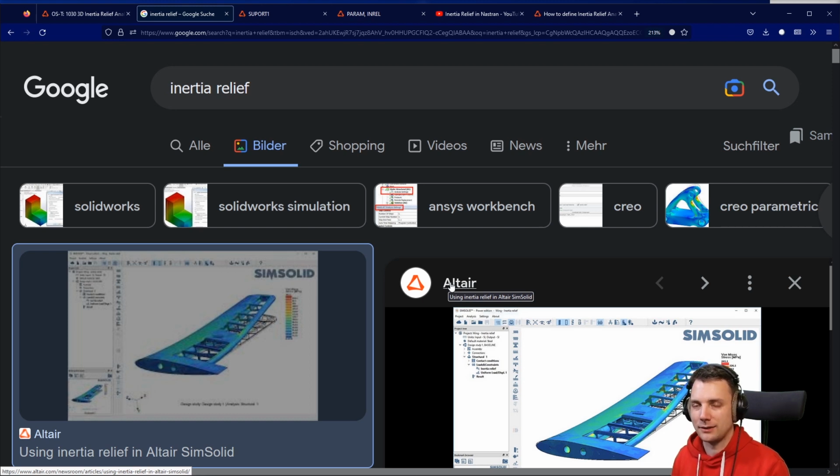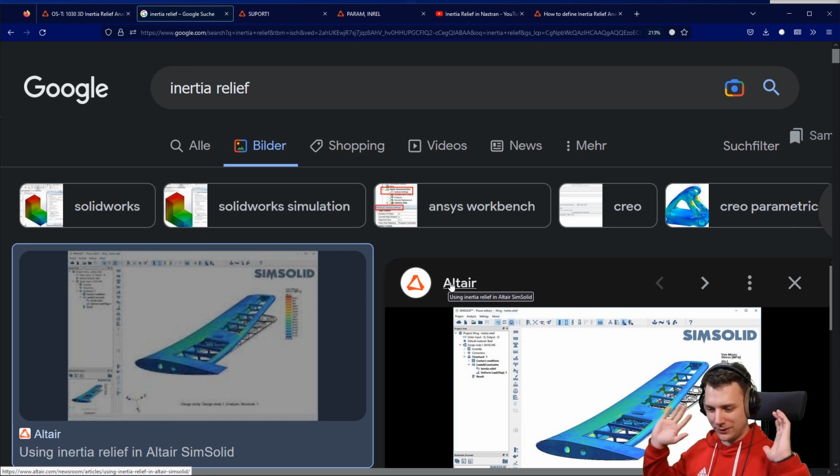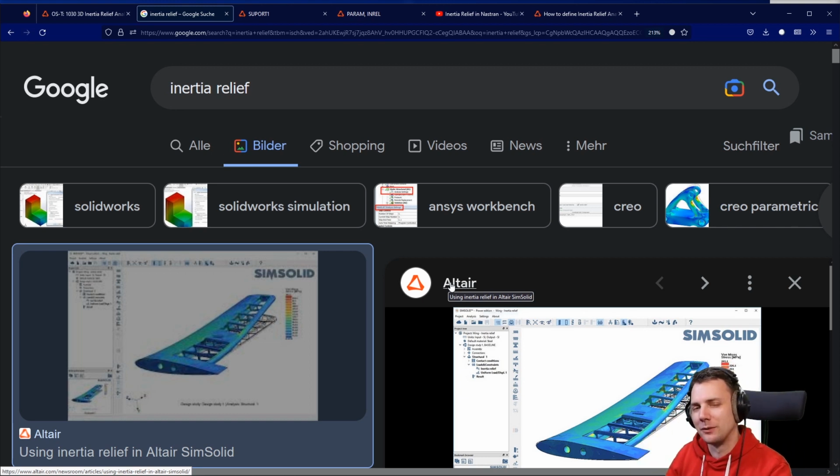And this way you can get pretty complicated analysis scenarios. Imagine you would have the plane again, you have the weight, you have the lift, you have maybe turning loads, you have the wind, whatnot. But with inertial relief, you can just throw all those loads onto the model, and the model will almost figure out how to constrain itself. Maybe you have to specify where the point is where you want to sum up all those loads and balance those loads out, and that's basically it.